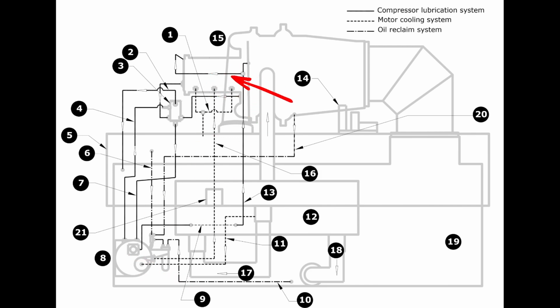So if you recently did an overhaul and the pump was working fine prior to it, and then suddenly one day it just stops without any warning, it wasn't having any symptoms, and it won't spin over, that's one of the first things you really want to check. It's probably not a bad pump necessarily. You probably got a piece of debris that pulled up in there and locked up the pump. Hopefully you haven't torn anything up in the process, and you can just pull that debris out, seal it, put it all back together, and you're back online.